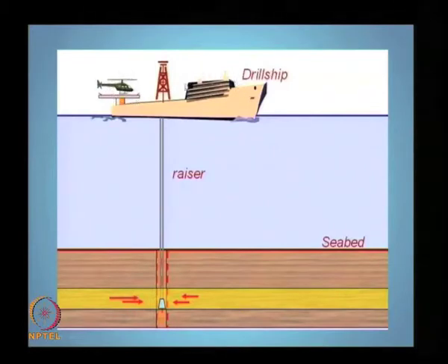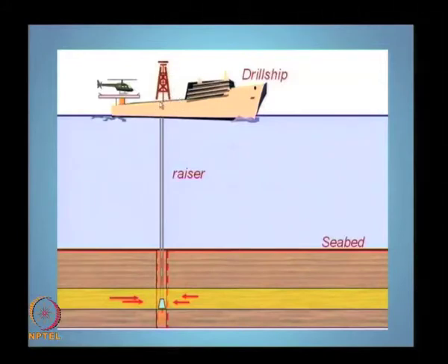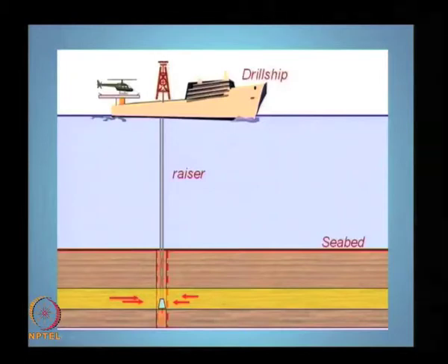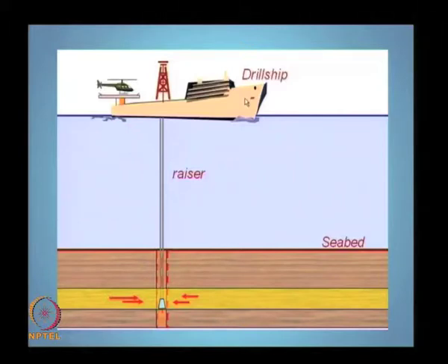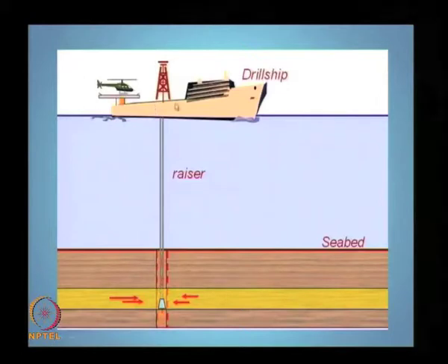These are the living quarters and mechanical and electrical equipment used for maneuvering the ship. The red one that you see here is the derrick, which houses all necessary plants and equipment required for drilling. The dynamic positioning system housed at the under hull will enable the drill ship to be positioned exactly vertically above the drill hole where the drilling has to take place.